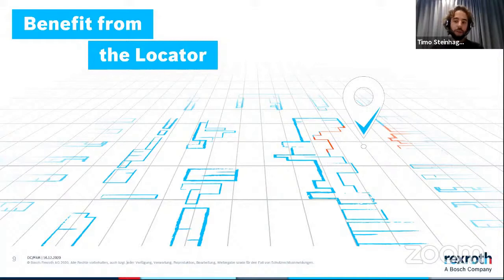And what I mean by flexibility is, for example, that we do not need any additional artificial infrastructure, but we use the laser sensor as our main sensor. And we just use the existing infrastructure to build our map and to localize on it. We can even use safety laser scanners that are already present on an AGV, so our customer doesn't have to add any specific hardware for a solution, but he can just install a software and use for localization.